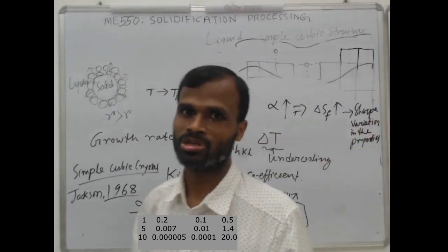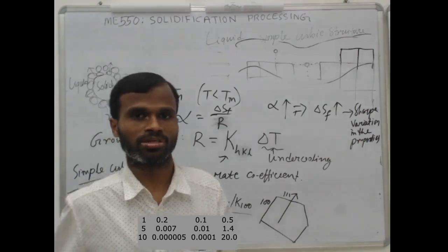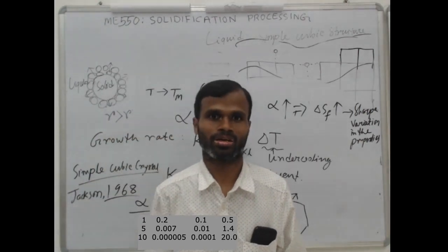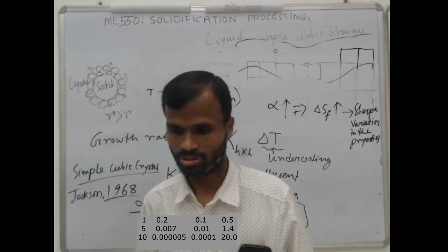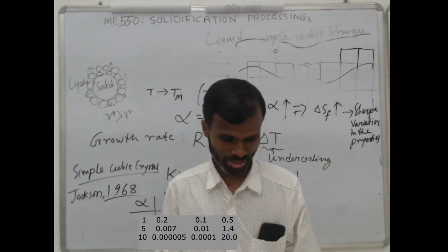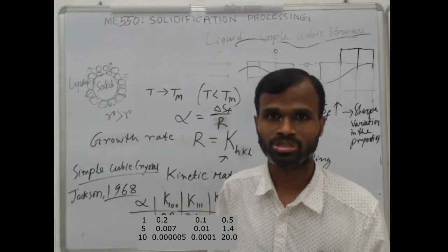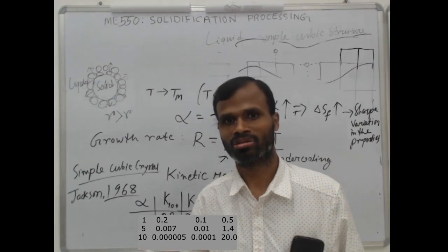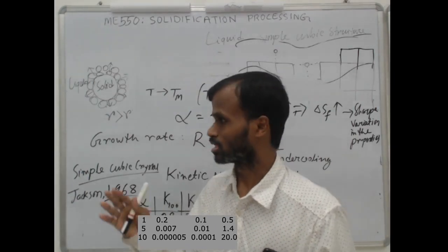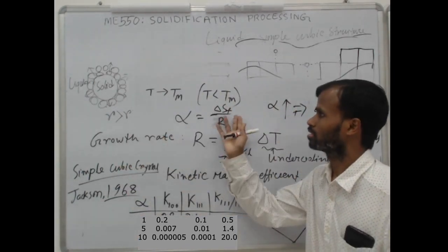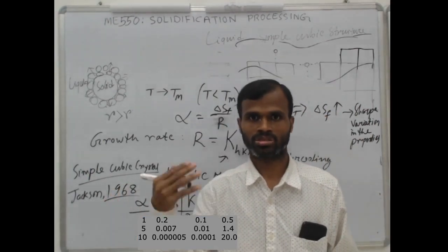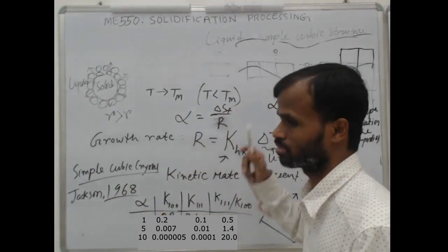And when there is sharp variation in the properties, you will have faceted kind of crystal growth, planar crystal growth, and it is difficult. You have to go for higher undercooling. But you should have defects like screw defects or twin boundaries. Other kinds of defects can be removed by the attachment of atoms and will not give any advantage if your process involves higher entropy of fusion.